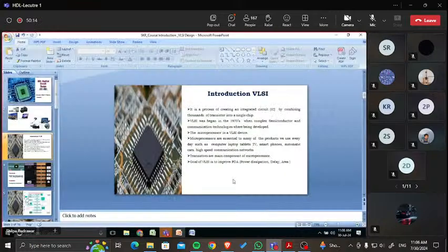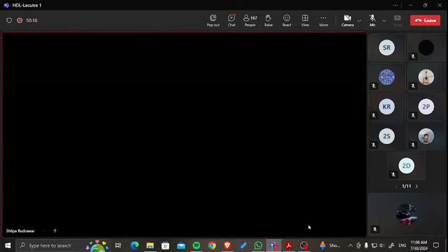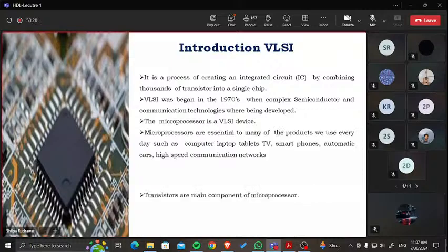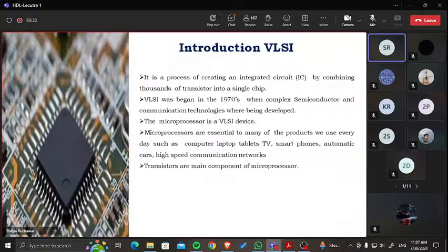Okay. So over here, CMOS is used because it has advantage over the BJT. It consumes less power. Voltage swing is more, so there will not be any losses. If I'm giving 5 volt, I'll be getting 5 volt. If I'm giving 0, I'll be getting 0 volt. Many times there will be voltage drop, and that's why instead of 5,